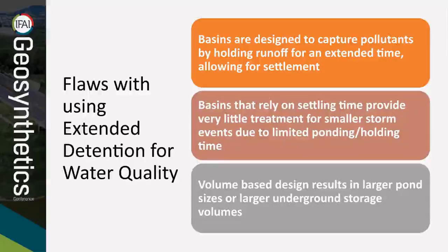The basins that rely on settling time provide very little treatment for smaller storm events due to limited ponding or holding time for smaller storms. In addition, the volume-based design results in larger pond sizes or larger underground storage volumes, which don't necessarily provide an increased benefit.